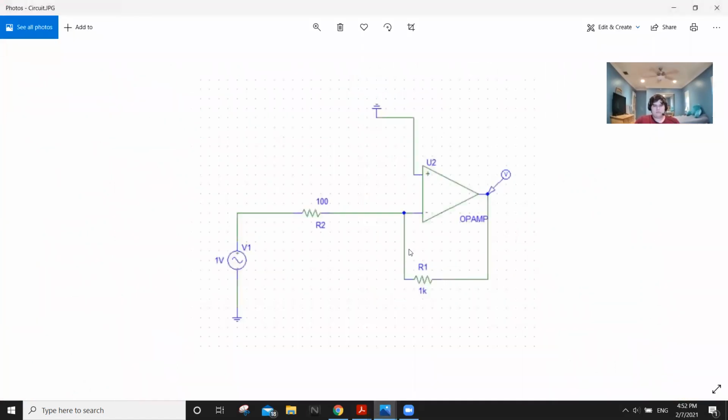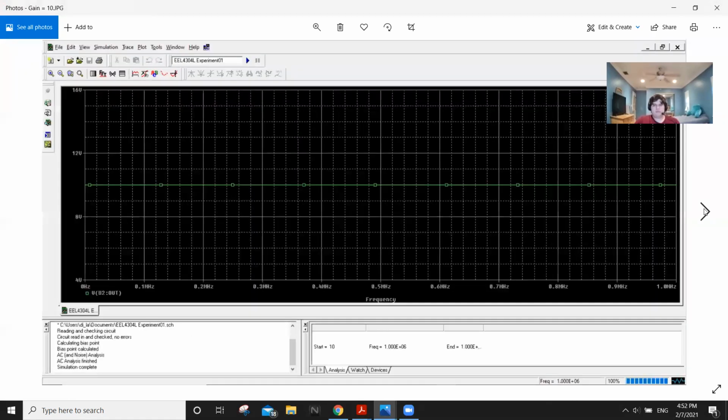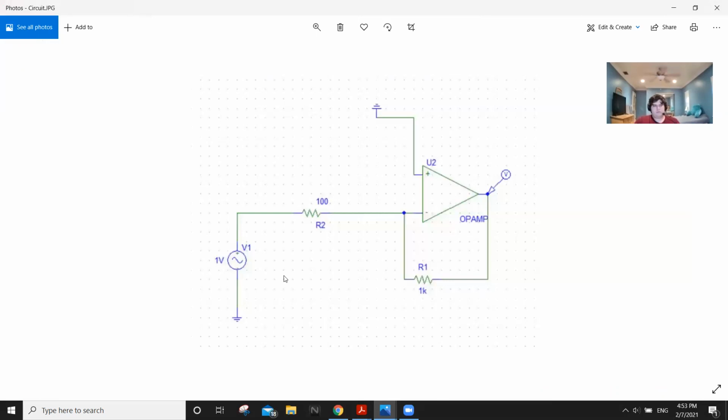To the simulation part, this is the circuit that we simulated on PSpice. The op amp uses an ideal op amp, so that's why we're not going to be able to analyze the slew rate and other aspects of the circuit, just the gain itself based on the AC sweep. So applying the resistance quotient that we mentioned before in the PDF file to get a 10 volt gain, we observe that in an AC sweep, we're going to have a 10 volt gain based on a 1 volt input that we're putting right here.